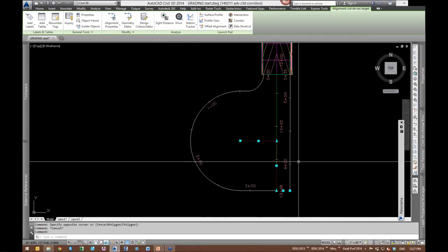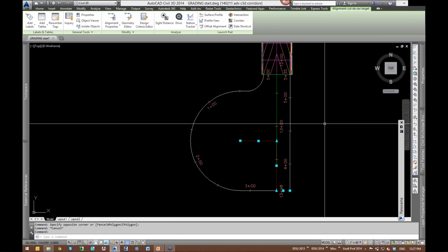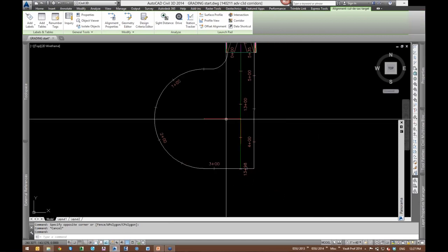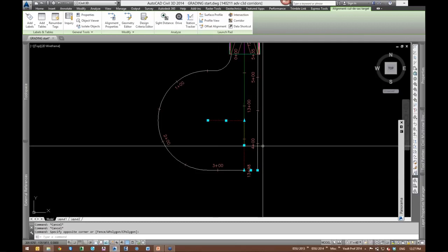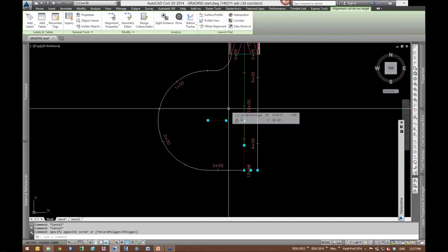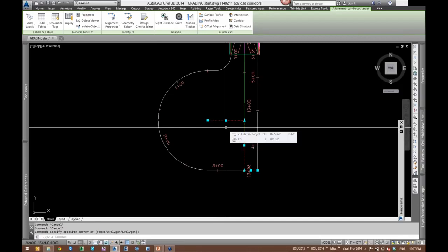If I can do this all in one region, that would be ideal. One assembly, one region, much simpler to work with. And here's the trick. We can use that same auxiliary corridor surface as the target profile. So we're defining the entire sheet drainage of this cul-de-sac, and then we're just placing alignments wherever we need them to manage our corridor targets so nothing overlaps.